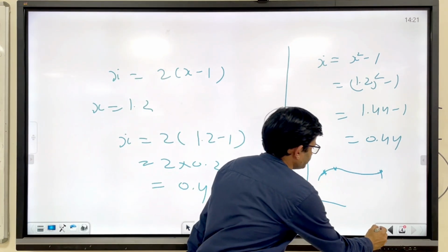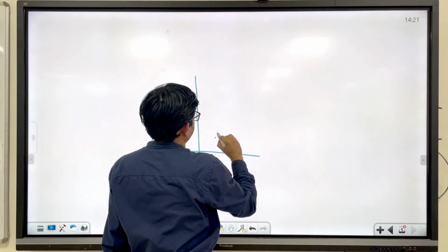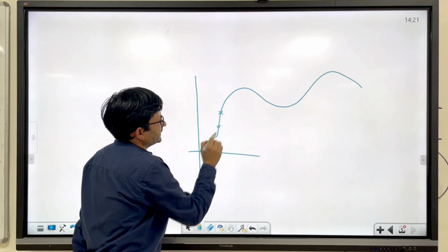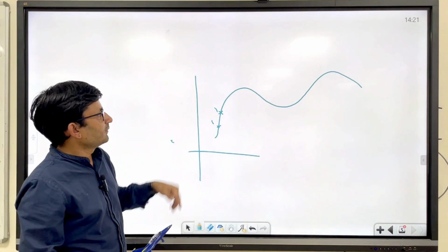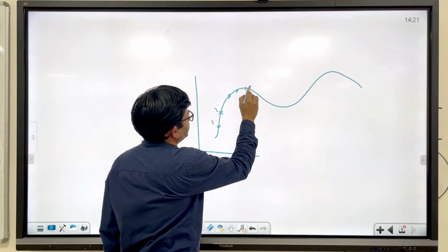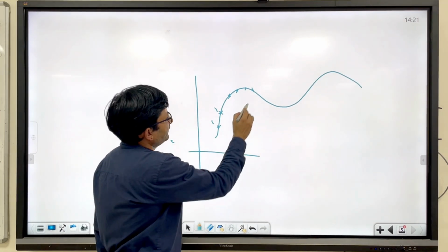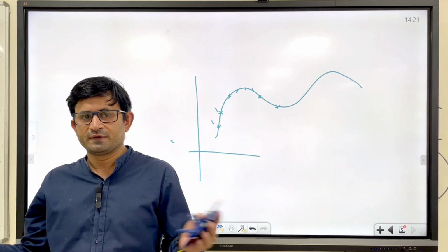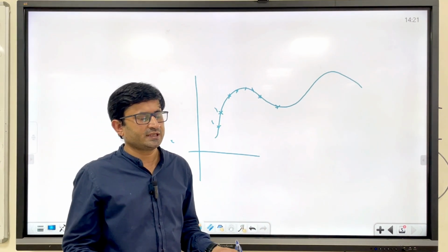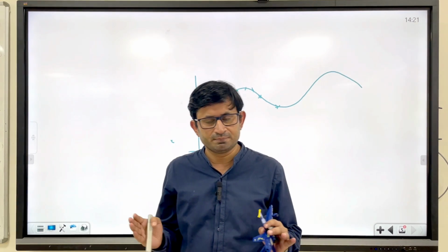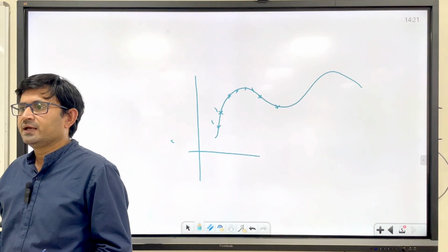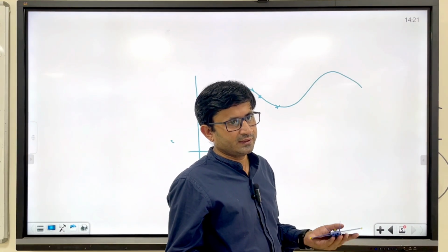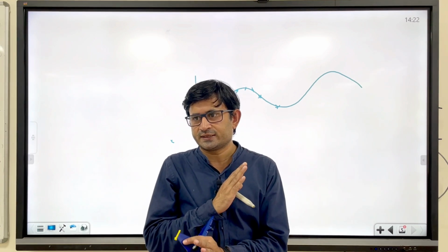For example, let's say this is any arbitrary curve. You will focus the linearization here, but you will not linearize here, because this is linear only, right? Then you will do multiple linearization here, because it is a curve, right? But here, 2 points are sufficient. So like that you have to perform the linearization at different trim points. So that is the purpose of linearization. It will simplify your analysis. And why do we need to simplify analysis? Because we have to design the control system for an aircraft, right? So the linearization part is clear, right?